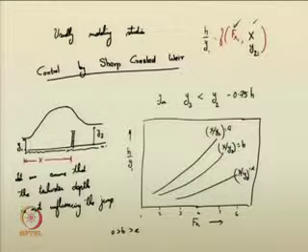So, if the x by y2 ratio is small, your h by y1 versus Fr1 curve will be looking like this. If it is a little bit greater, it will look like that. For higher values of x by y2 ratio, it will be looking like this. Like this, you can prepare curves, and based on that you can appropriately suggest what could be the height of the sill given the following criteria. For a given Froude number, if that Froude number is maintained, you can suggest that if the x by y2 ratio is a, then the h by y1 ratio should be the following. One can easily interpret this for designing.